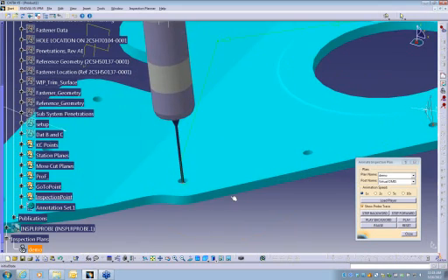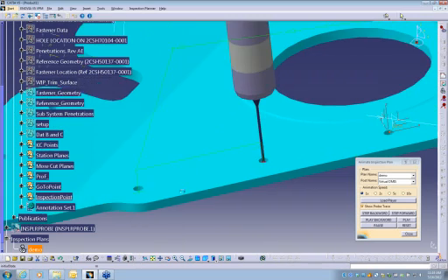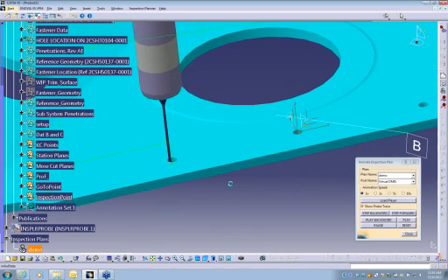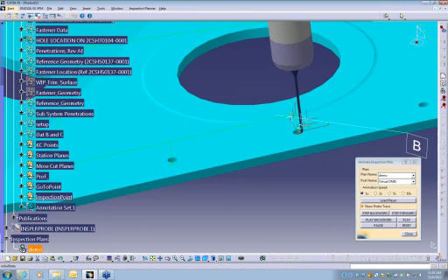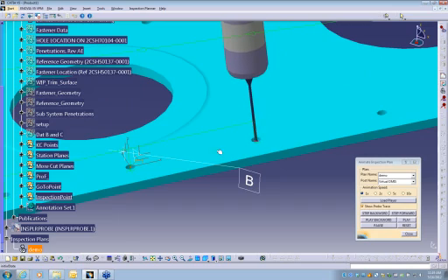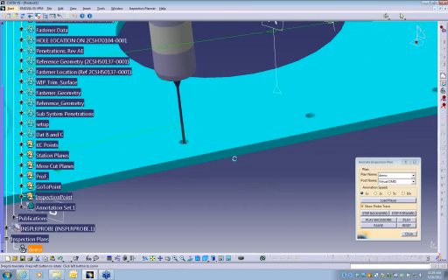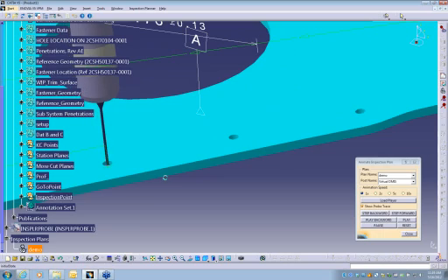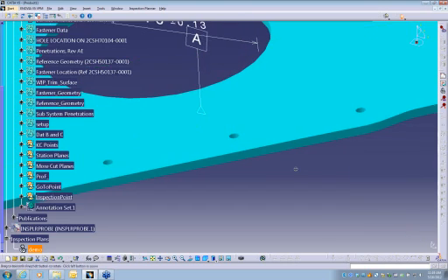And you're going to see the 4 hit points inside the hole. And then it's automatically going to create this 1/4 inch go-to move that comes out of the hole. So there's a lot of time saved by the planner calculating all the motion of the probe. And like I kind of said on the PDF, when we post this, we also give you an APT source file if you wanted to run this in other CATIA NC processes for collision, or if you wanted to run something like VeriCut, it would check for any collisions that you might have. So you kind of get the idea there.